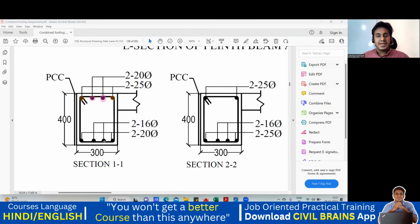Okay, good. Next, come to the bottom portion. In the bottom, we are supposed to provide a 20 diameter 2 bar and a 16 diameter 2 bar. So this outer one will be my 20 diameter 2 bar. And then the middle one we have is the 16 diameter 2 bar. This will go completely throughout the length.